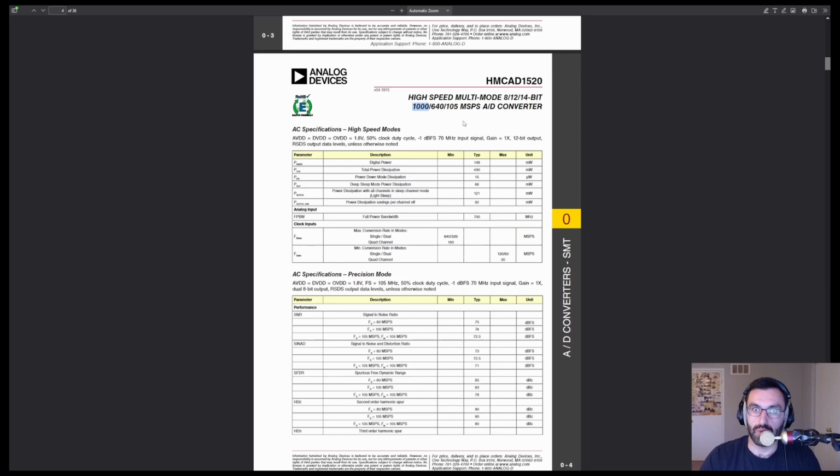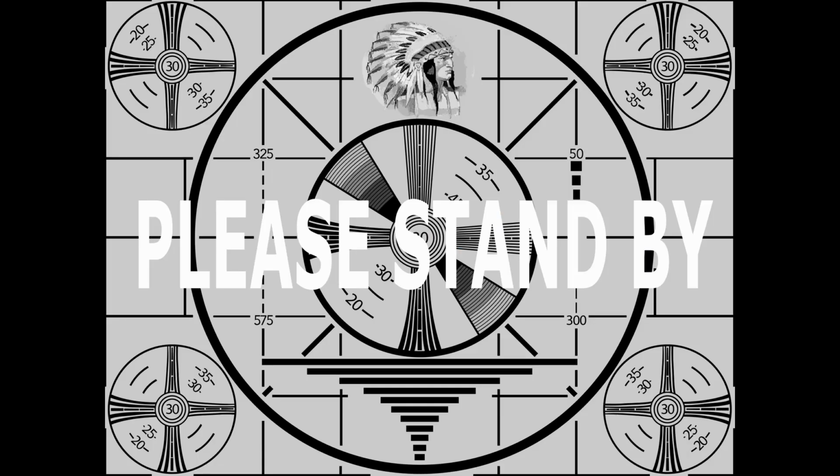So that is the bandwidth on one channel. The bandwidth on 2 channels is roughly half that, so 200 megahertz, and the bandwidth on 4 channels is 100 megahertz. And then if you go into 12-bit mode, you have that still. So editor's note, I switched to sample rate here. If you want bandwidth, like I was just saying before, divide by 2.